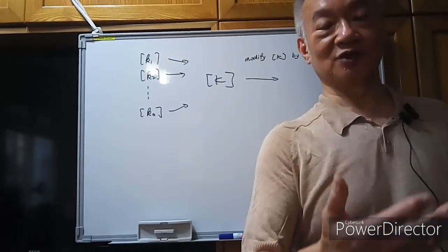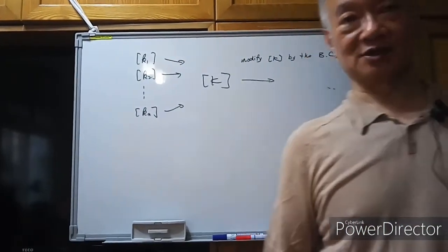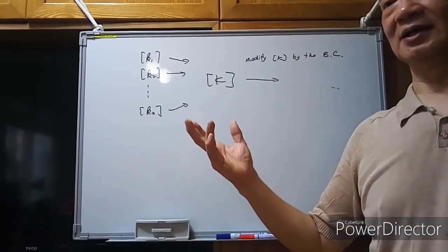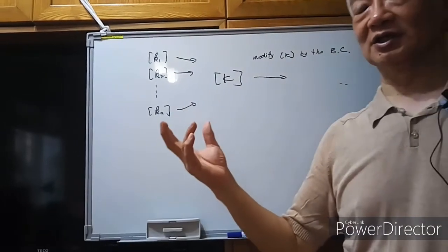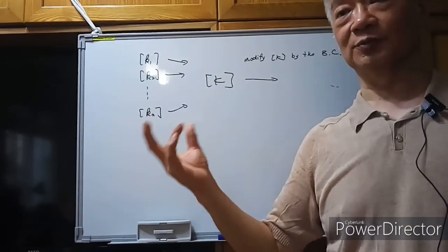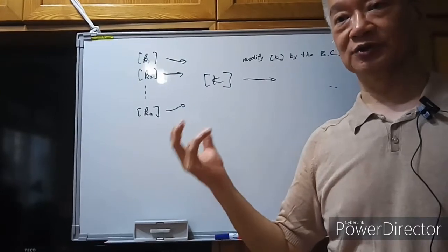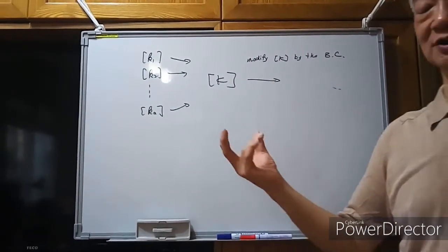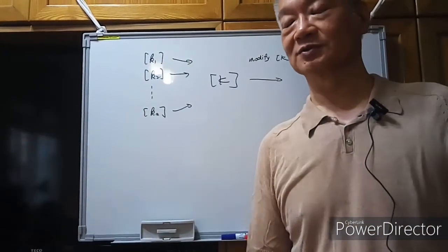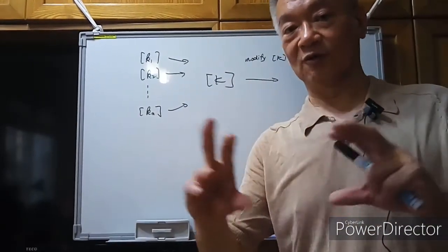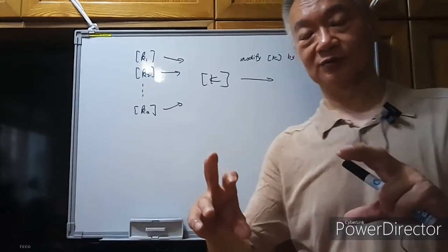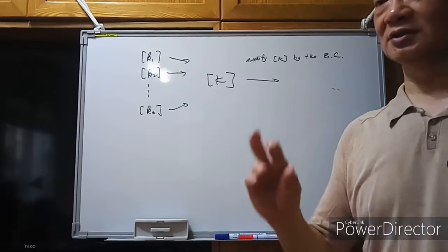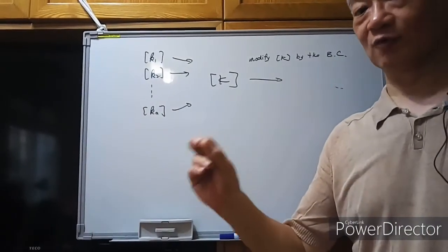For example, if we use the 4-node element, for some elements all 4 nodal points are related to unknown displacements, but we know the resultant loading applied to those nodes. For some elements, all 4 nodes belong to the unknown displacement but known force.